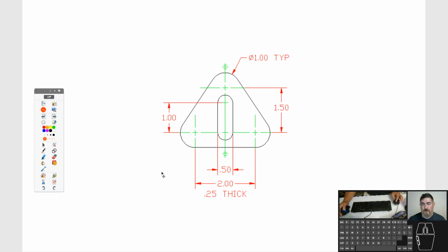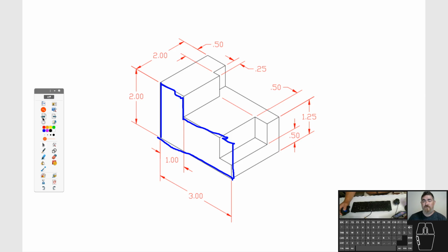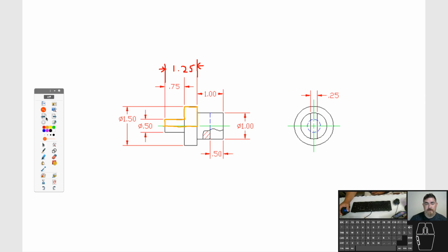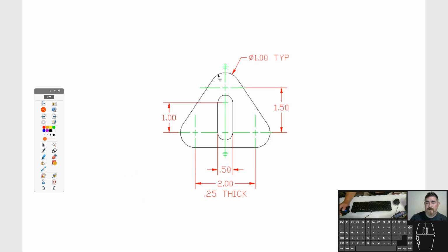All right, last one. Ooh, this one's a little different, right? So far, we've been doing things with just square corners in the sketches. And usually you'd want to do that. If you can draw it with a square corner on your sketch, that's better than drawing something with fillets. Even if these edges were filleted, I would still draw it the same way, and then I'd come back with a place feature and add the fillet on that corner, because I have the overall dimension and I can draw it with square corners. So then you want to draw it with square corners. Adding the fillets into your sketch makes things more complicated.